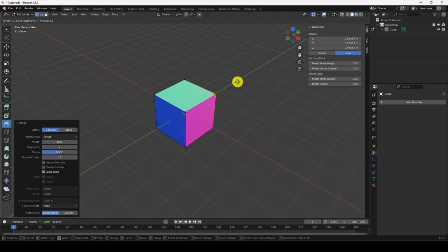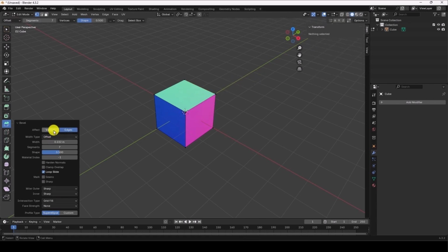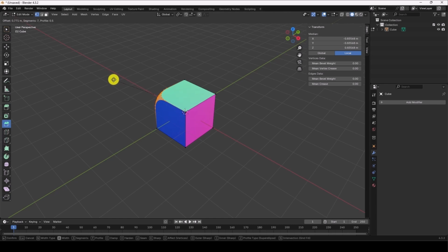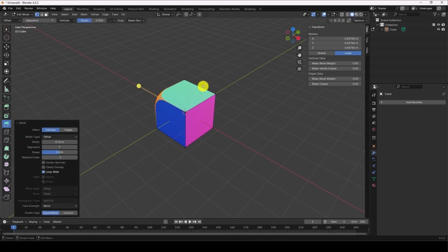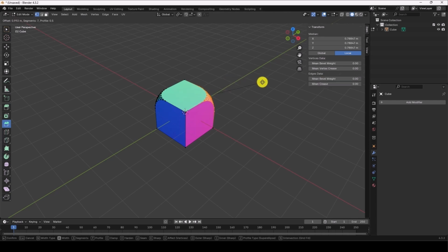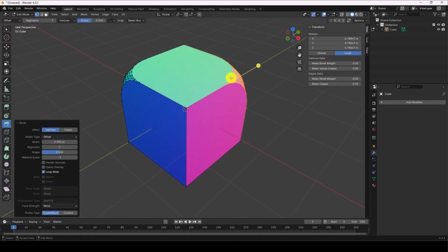the corners beveling. Even if you haven't selected the Vertex option from the menu at the bottom left corner, beveling will still work if you have Vertex mode enabled from the top menu. Select a corner, move the mouse, and you'll see the vertex or corner being beveled. It's important to select Vertex mode from the top menu when working with vertices.